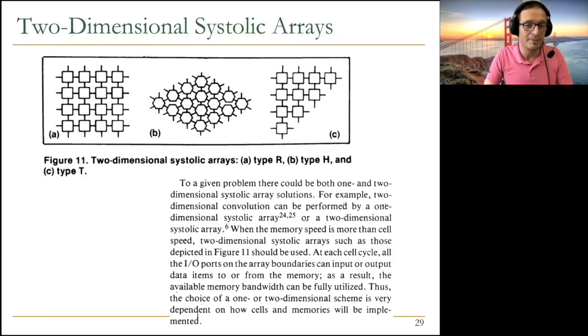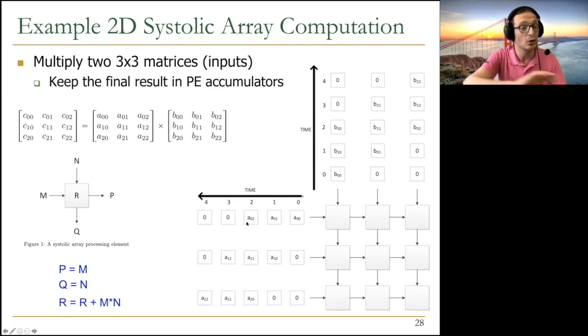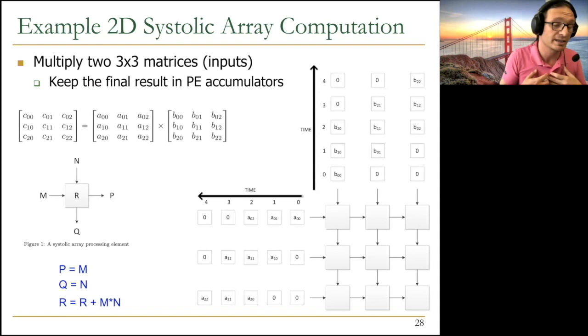By the way, if I go back to here, this is the matrix multiplication, right? Here, we basically stored the matrix inside the processing elements. We didn't have to do that. There's another way of doing matrix multiplication where the result flows out. But I don't show it over here, and maybe you can start thinking about it. Here, the result doesn't flow out. Results get accumulated inside the processing element, and eventually you get C00 over here, C01 over here, C02 over here. And later you need to read the result out sometime in some way.